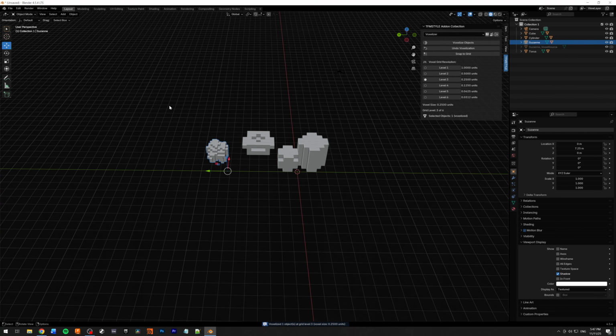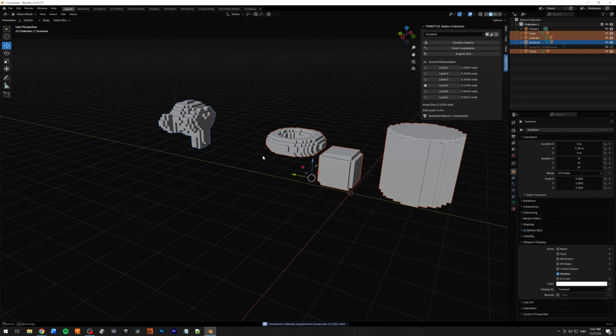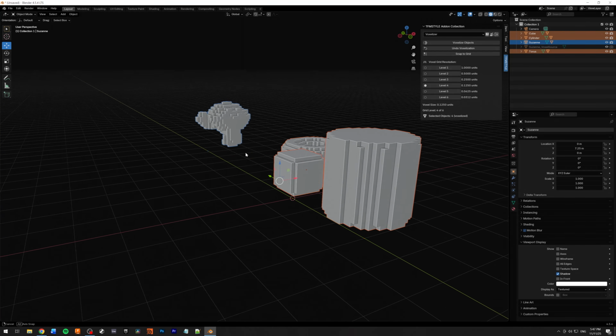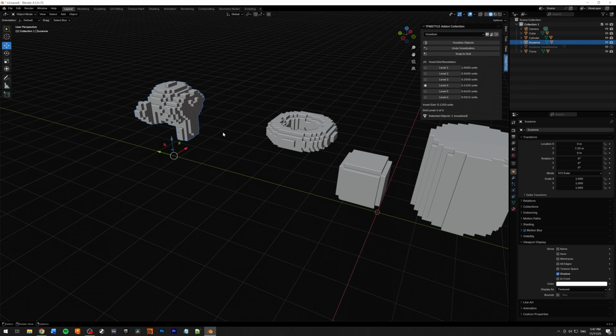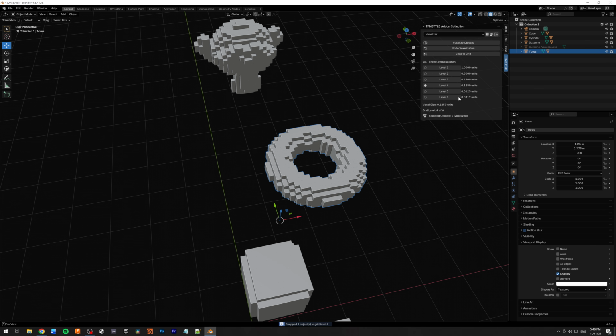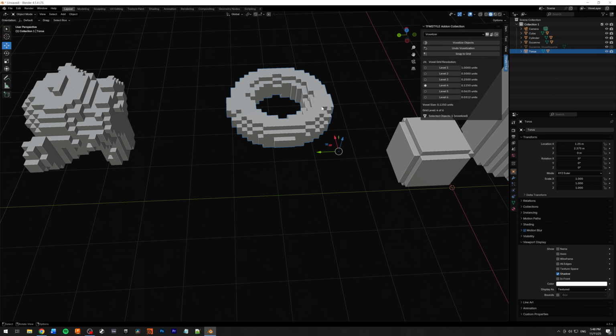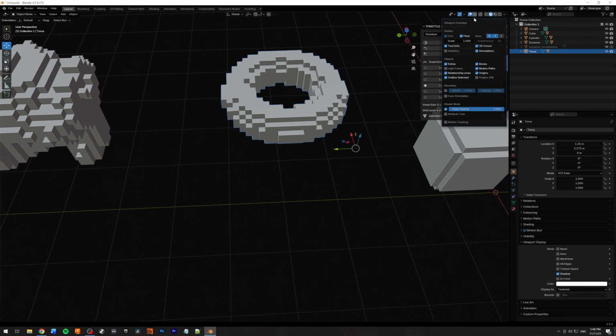And the nice thing is that now you can select all of them, go to level 4, voxelize object, and they are all going to have the same voxel grid resolution. They will have the right origin position, and you can even snap to grid. And in this case, if you want the floor to actually be the same unit, you can go to your floor.